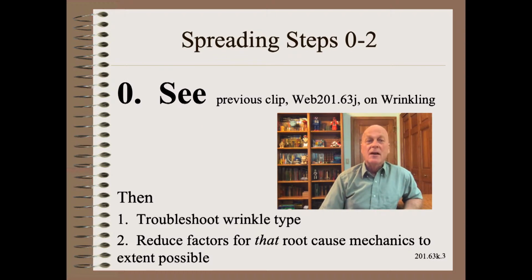Stronger factors are application dependent. If, for example, a specific wrinkle is caused by roller misalignment, then aligning rollers makes a lot more sense than changing tensions, which may not be effective enough, or adding a spreader, which is costly both for installation as well as ongoing maintenance, even if it helped.